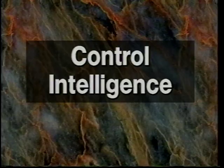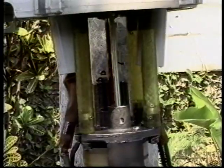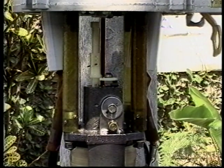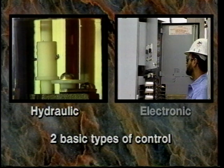Control intelligence. The intelligence that enables a recloser to sense overcurrents, select timing operation, time the tripping and reclosing functions, and finally lockout is provided by its control. There are two basic types of control schemes used: integral hydraulic control or electronic control located in a separate cabinet. A recloser employs one of these controls.